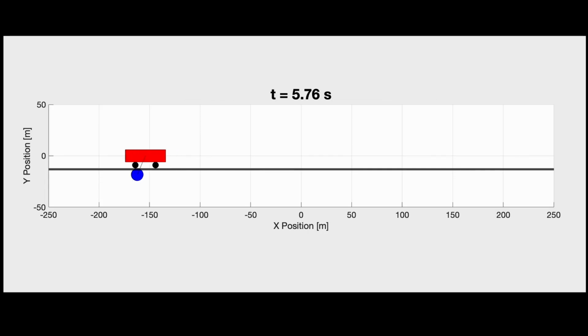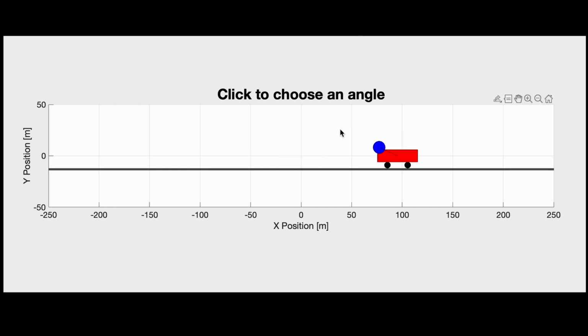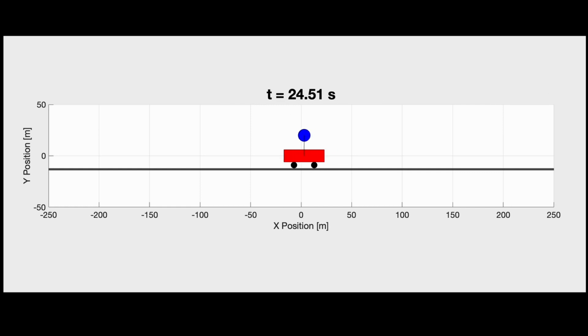This way, with a combination of the desired energy controller and Linear-Quadratic Regulator controllers, we can stabilize the pendulum from any position. Please note that if you build the system, you will need to tweak some of the parameters and maybe change the dissipated energy formula for the best results.